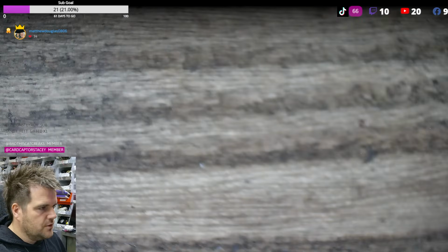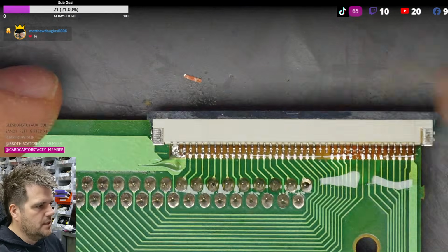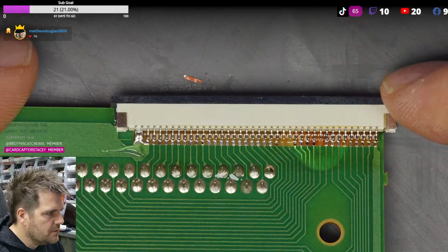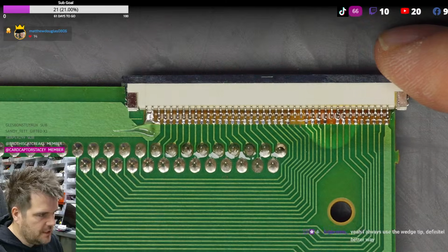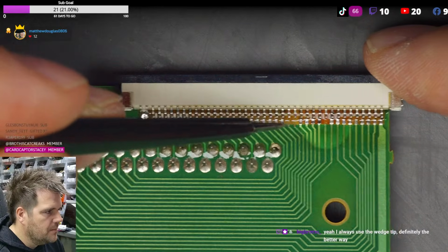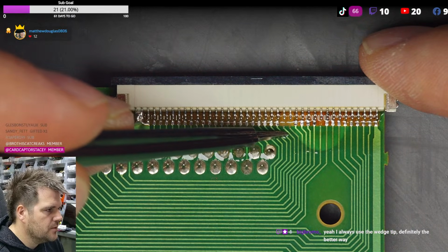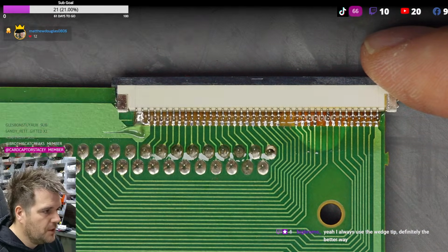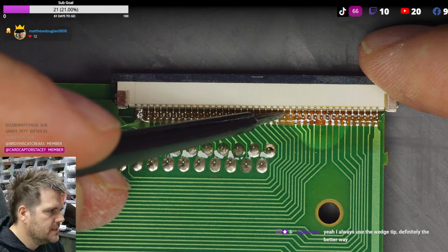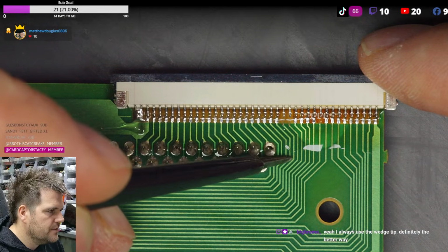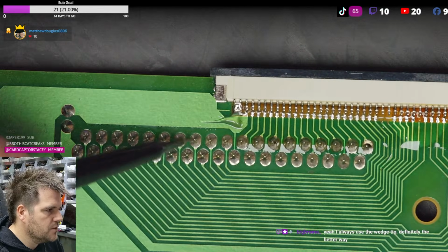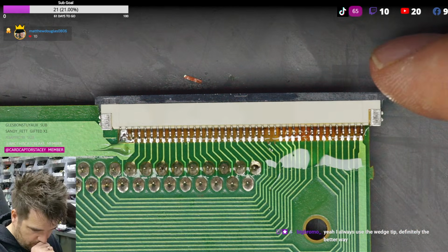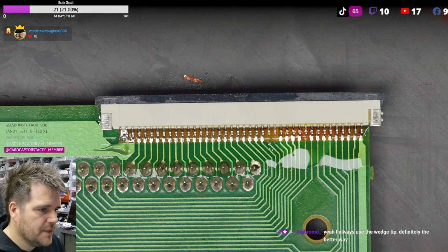So now all we have to do is restore them 2 pins. I think that was the only thing. So you've got 2 options here. You can either do a nice clean connection, which is to grind away this and do a little wire join here, which is probably what I'll do. If you're not confident in that, you can tack a wire on here, follow this trace around, go all the way wherever it goes and connect to the big pin here.